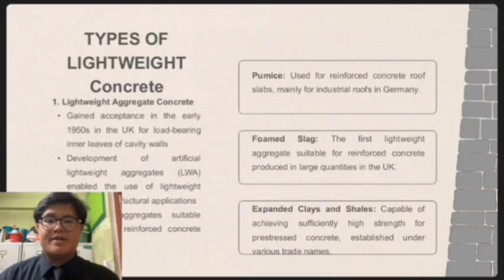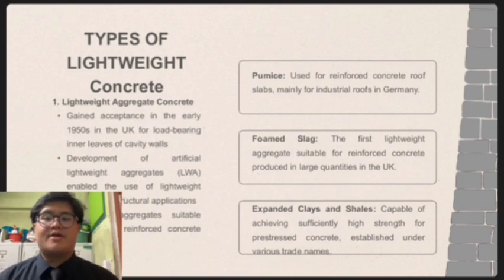I will explain the type of lightweight concrete, focusing on lightweight aggregate concrete. This type became popular in the early 1950s in the UK, especially for load-bearing cavity walls. The development of artificial lightweight aggregate allowed this concrete to be used safely in structural and reinforced construction.